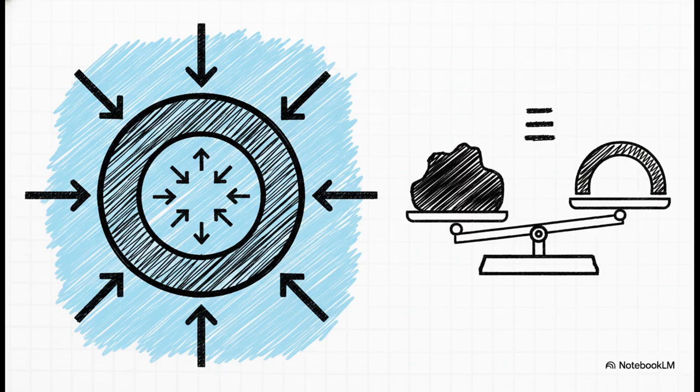And to make things even more complex, high-pressure subsea pipelines require incredibly thick walls to resist both internal fluid pressure and the crushing external hydrostatic pressure of the ocean. That thickness entirely alters the pipe's weight and stiffness, which complicates the stress profile even more.